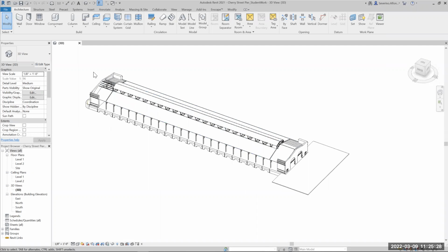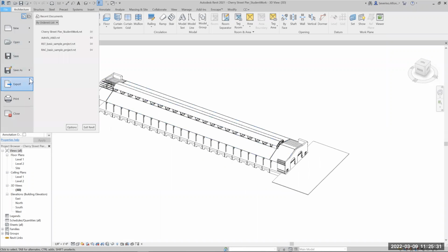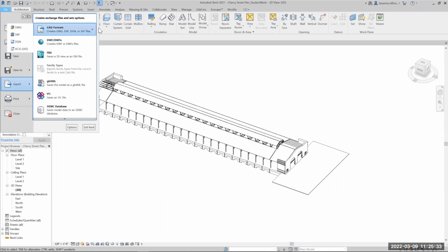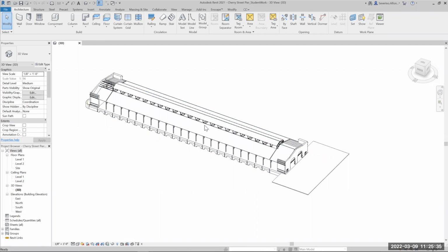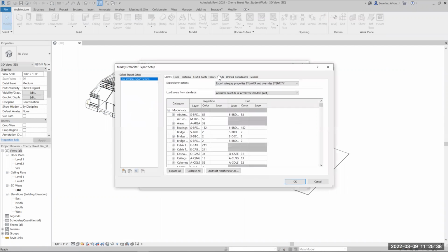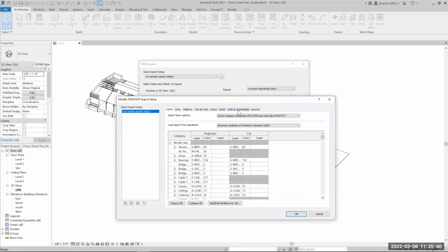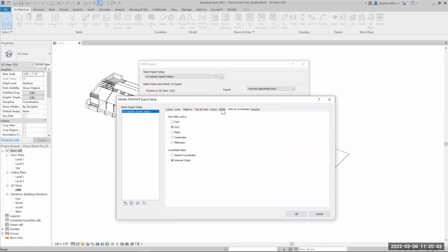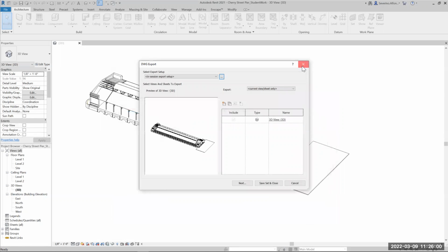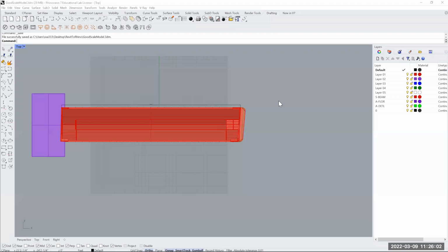As you know, I'm going to the 3D view normally and say File, Export, DWG, and I already exported this two times. Clicking on the three points here, one of them was set to inches and always as solids, and that was wrong, because we wanted it in foot. And the second one I did correctly, setting this to foot and not inches, with the same condition as solids.